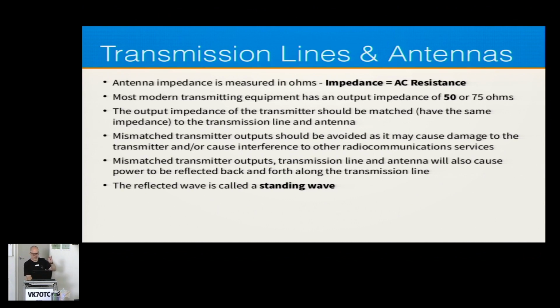We introduced the concept of impedance, which is AC resistance. Most of the transmitting equipment that you will be exposed to is 50 ohms. Televisions still use 75 ohms, so if you plug in a television antenna, it is actually 75 ohms. And the output of the transmitter should be matched to the characteristic impedance of the...